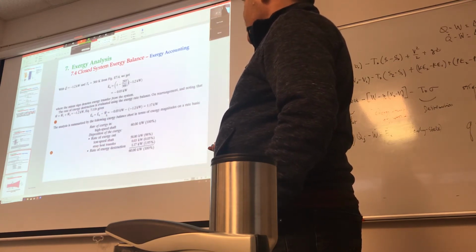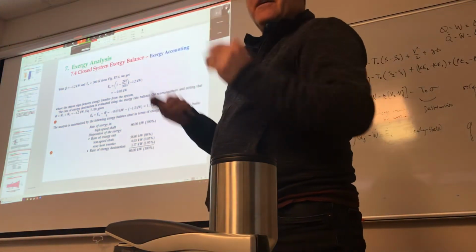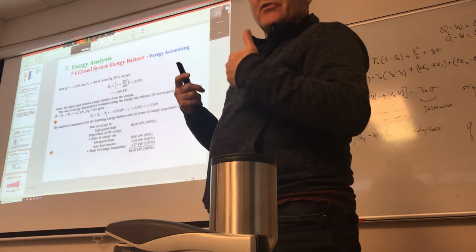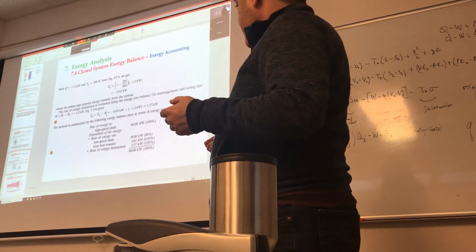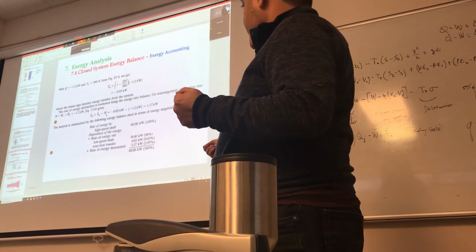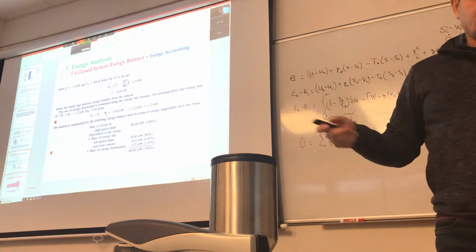The stray heat transfer, the Q that's coming out of the shell of that gearbox, constitutes an exergy loss, an exergy exchange, right? Which is 0.03, and the rest of it will obviously be destruction, so you accounted for all of it. Okay.